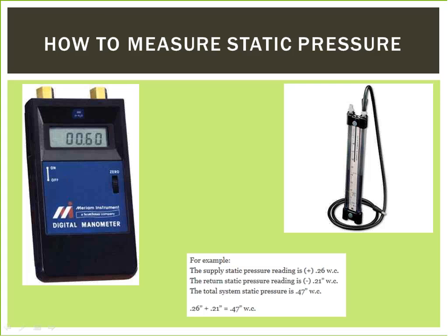Step 3. Push one end of the tubing onto the static pressure tip. Place the other end of the hose on the high pressure port of the gauge. If required, make sure the gauge is level and zero the gauge by adjusting the screw on the face with the small screwdriver. Digital gauges each zero differently, so check the owner's manual.